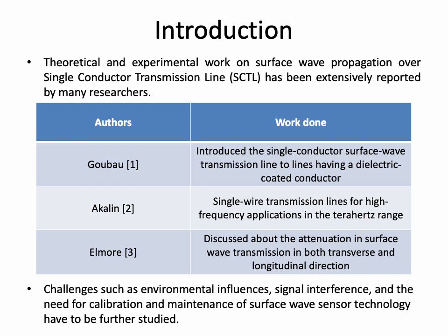Additionally, the wave also undergoes attenuation in the longitudinal direction due to several factors, including the finite resistivity of the wire as well as the dielectric loss and leakage in the surrounding medium. So these were the topics discussed by Elmore. Apart from these, challenges such as environmental influences like rain, fog, and dust, signal interference, and the need for calibration and maintenance of surface wave sensor technologies have to be studied further.